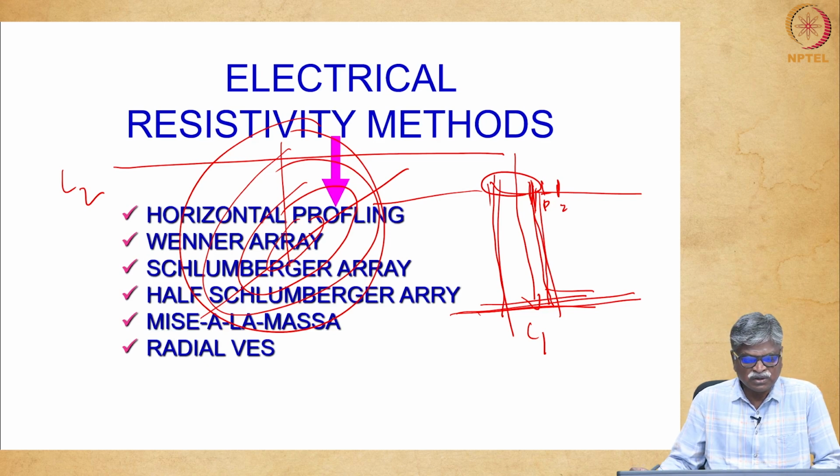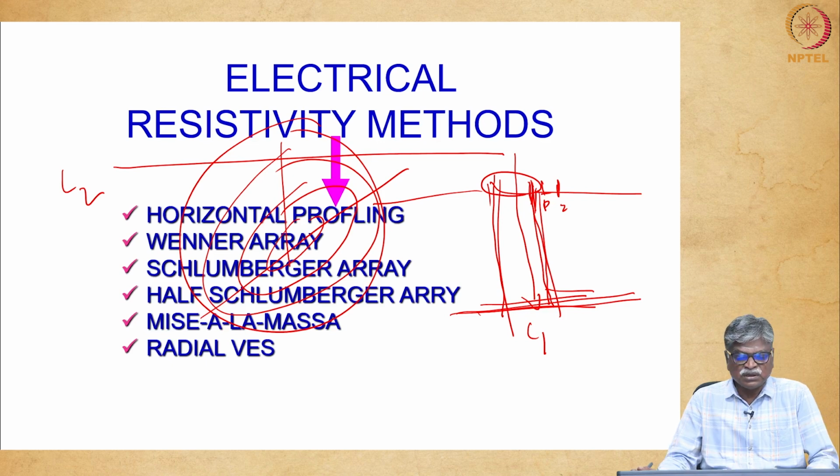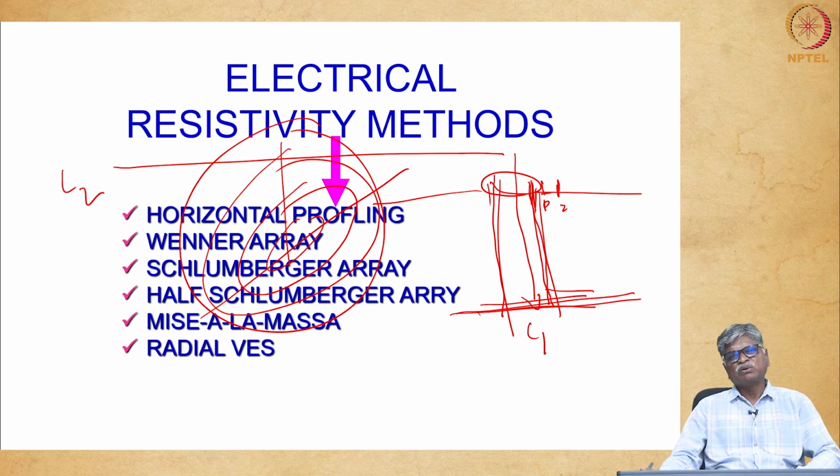This miscellaneous method is useful for finding where the cavity is in that area. Another use: instead of the radial VES, after drilling the borewell, wherever you got the fracture, we can also do this miscellaneous method there. So the orientation of the fracture you can easily find out.